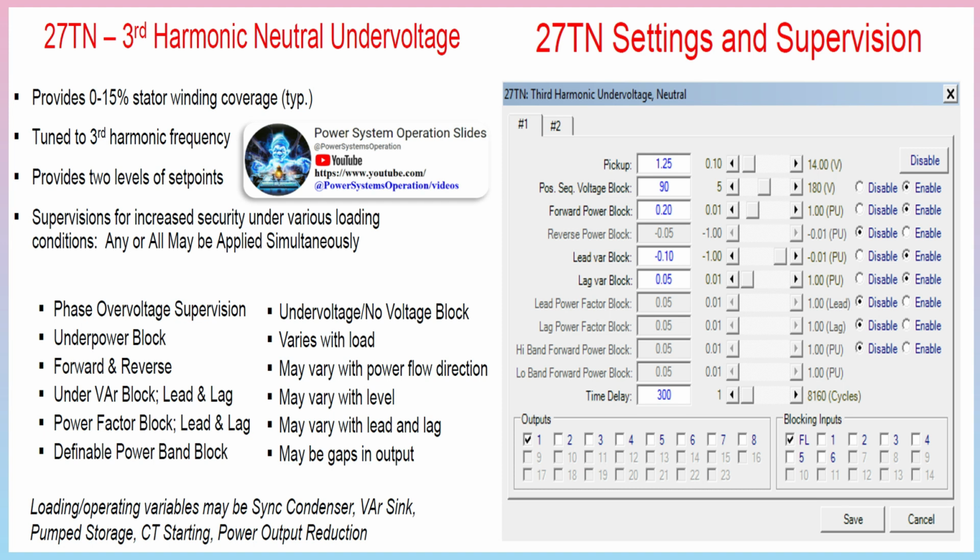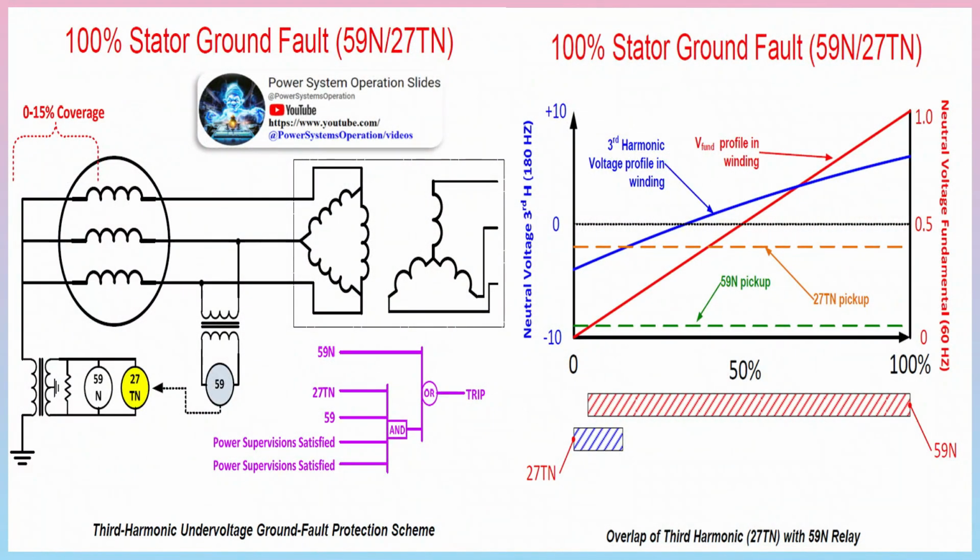Unbalanced stator loading protection. Unbalance in loading produces negative sequence currents in the stator circuit. This negative sequence current produces a reaction field rotating at twice synchronous speed with respect to the rotor, and hence induces double frequency current in the rotor. This current is quite large and causes overheating in the rotor circuit, especially in the alternator.